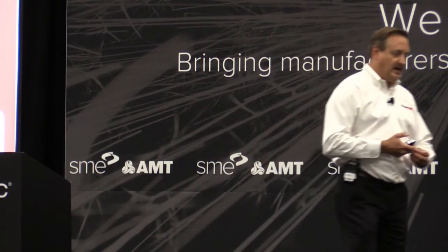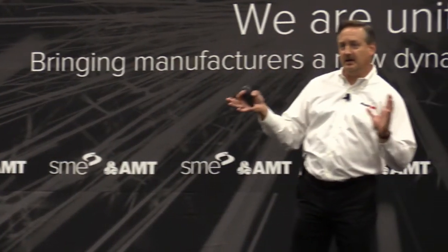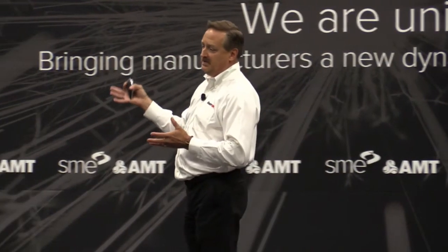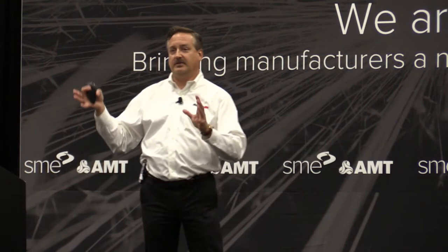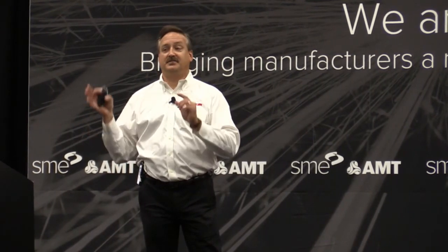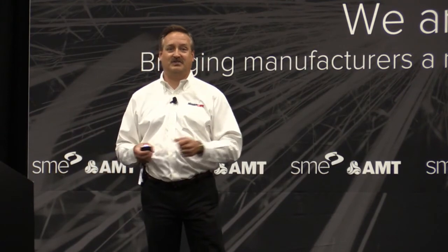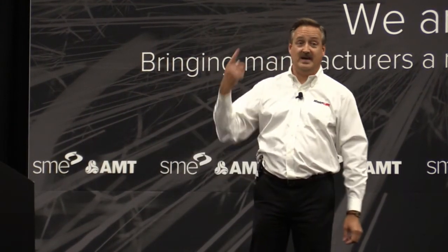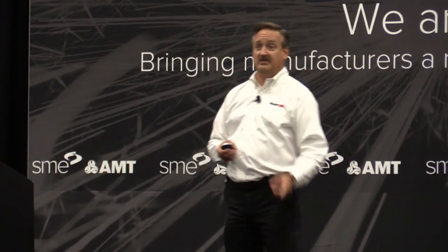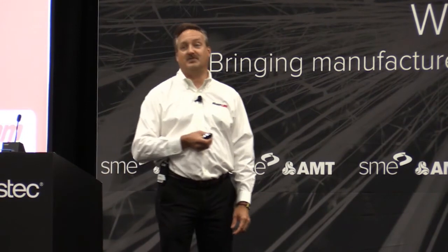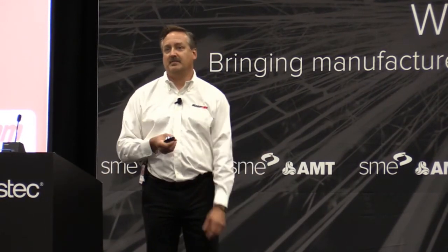Yeah, in most shops, ballpark, and this is coming from industry, even from tool vendors, 3 to 5 is roughly the baseline. However, if you're in aerospace, or a job shop that specializes in HRSA materials or difficult materials, that tool cost is going to go up. It's going to be between 8 to 12. It might even go up as high as 14 or 15%. So it really depends on the application.